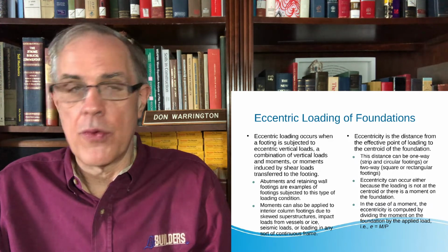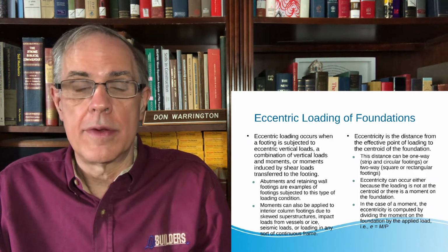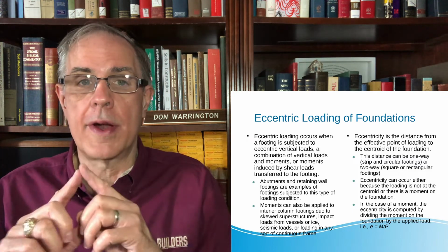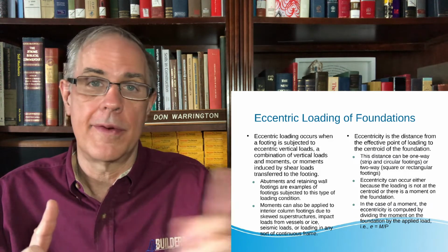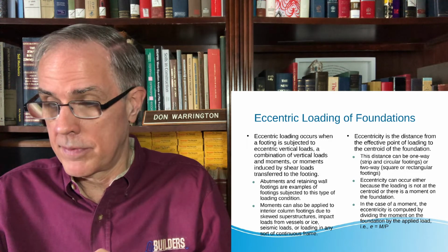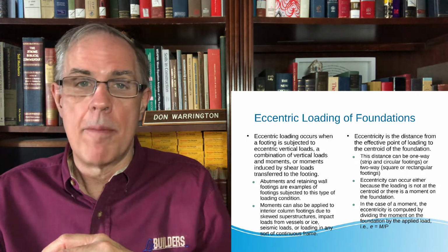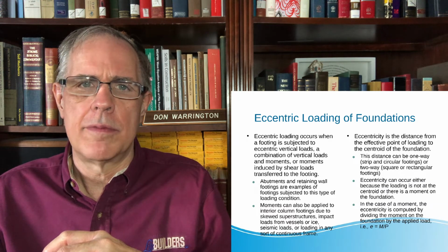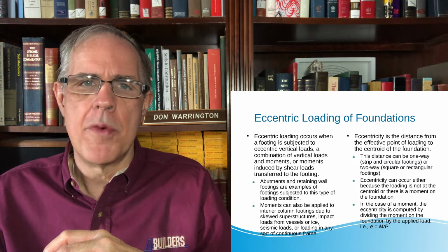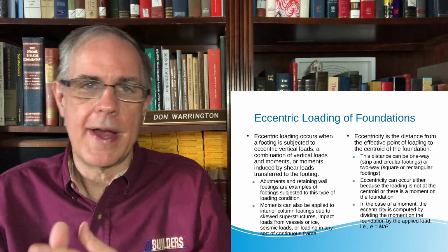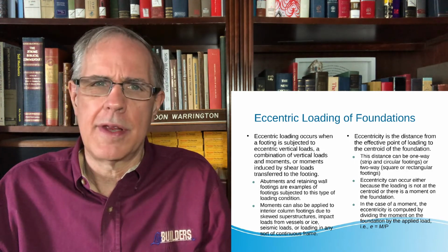And the distance can be one way or two ways. In other words, with a strip footing, you only have one way to go. With a square or rectangle, you can go either the X direction or the Y direction, or both. And it's important which one is both. You can have a moment, but the easiest way to deal with a moment is to essentially use the moment arm as the eccentricity and move whatever load you've applied over there. That's usually the easier way to do it.